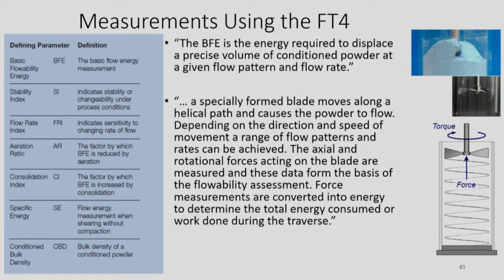I'll not be talking about Anton Paar, but I will talk about FT4. It's very common nowadays. It gives lots of parameters like basic flow energy, flow rate index, aeration ratio, permeability, etc. The instrument has a curved blade that passes through the powder.